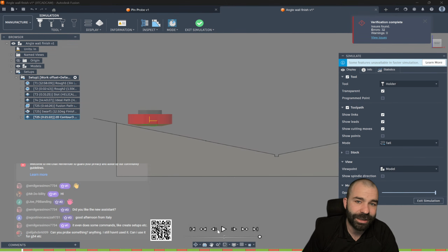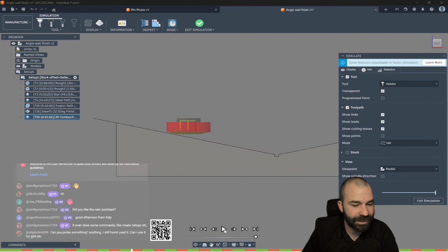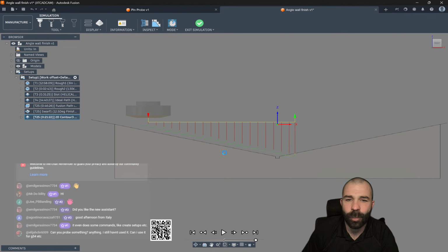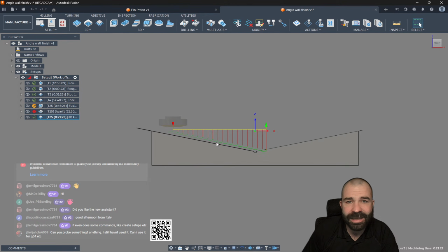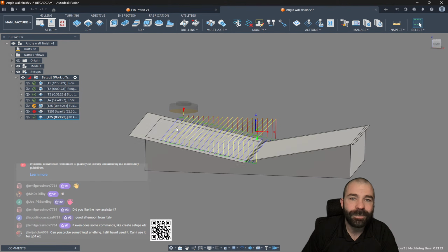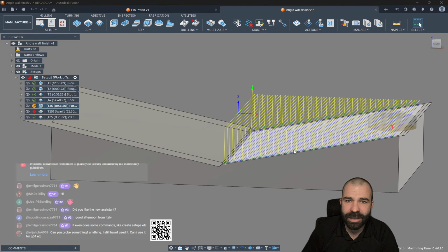I'm going to assume we're going to get closer the further we go down. And considering I was told 12.5 degrees, we're probably missing 77.5 degrees, right? Now, that is the whole goal there, is to be able to follow a taper, very simple profile here, and step down that wall consistently. Again, guys, I got the angles wrong here. But that is how you can utilize multiple depths at an angle, and your end mill would have to be a tapered end mill.